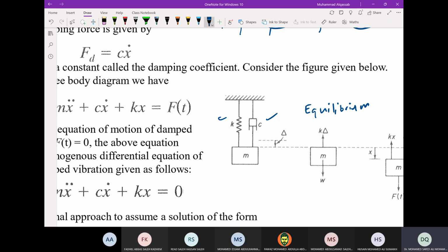It consists of a spring, a coil, and inside it there is the viscous damper. At equilibrium, the damper is not active because it is related to velocity. If the car is not bouncing up and down, the only element that carries the weight of the car is the spring, not the damper. The damper will be active if there is vibration up and down, so it does not carry static weight.